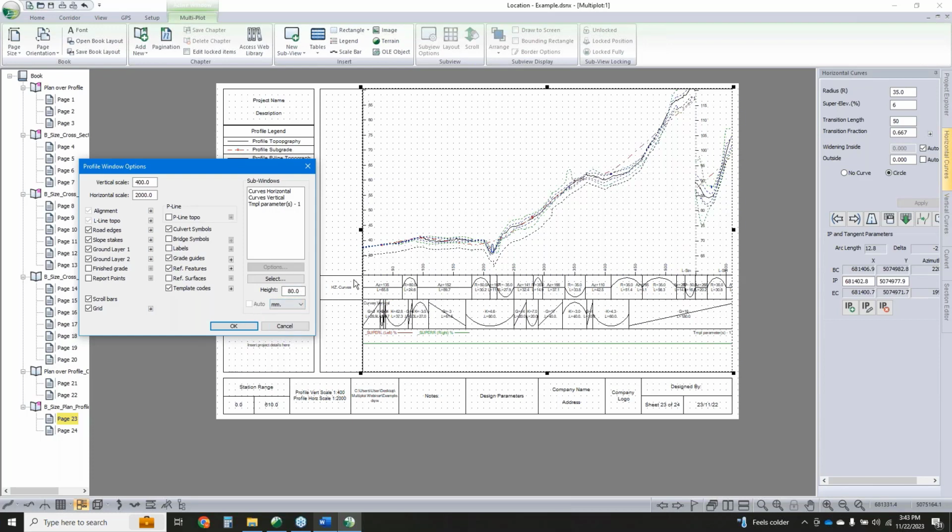And what I did is, so it's nice and easy to line up my rectangle text boxes with those items, as I made them all in the same increments. So I'm using a 5 mil grid, and I'm in increments of 5 mils. So it's really easy to line those up and have something that looks continuous as you're working along with it.